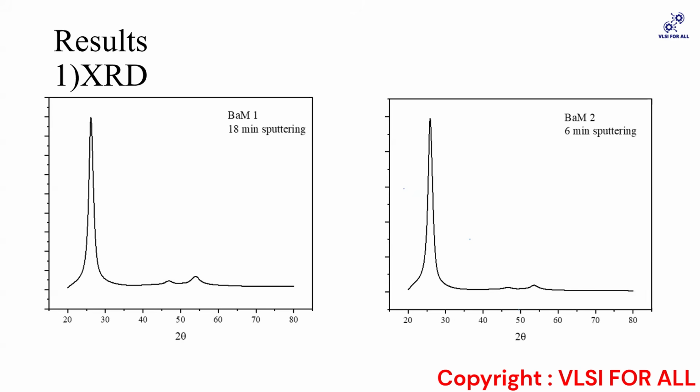So the difference between PVD and CVD can be checked here, because in PVD we are just going to check the physical layer. We are not going to change its interior characteristics, dimensions, or even orientation. Whereas in chemical deposition, we are totally going to change its properties. In CVD we need to heat up the gases, then heat the target and substrate, and then it is deposited layer by layer. Whereas physical deposition is the easiest process to deposit a thin film on the